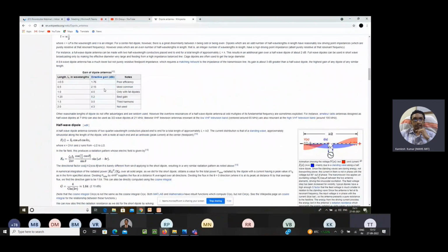So the simple calculation we'll be doing here is F is equal to C by lambda, wherein we'll actually get the lambda value. So this is how your dipole will actually work. You'll be exciting it with a source, either a delta gap source or any other source. So we'll get an 8-shaped pattern around your dipole antenna. This is a half-wave dipole antenna.